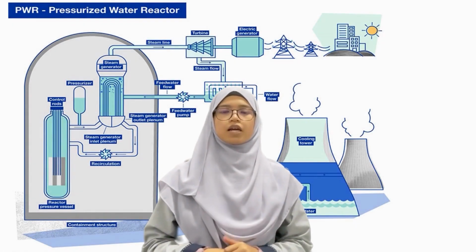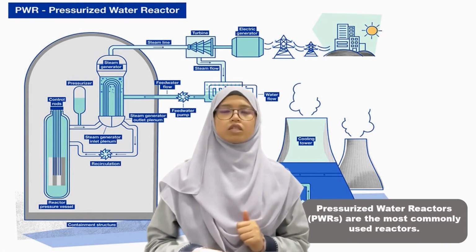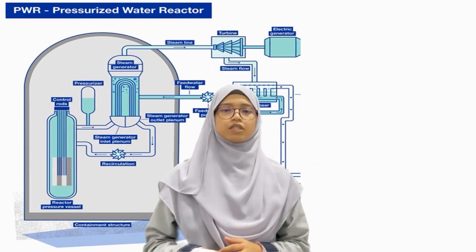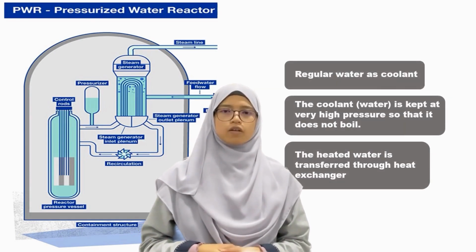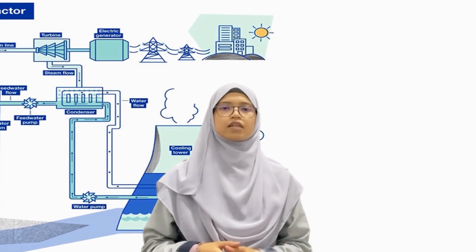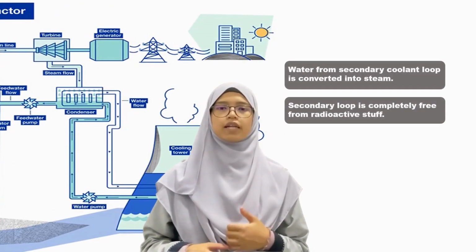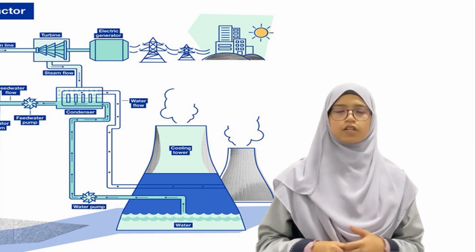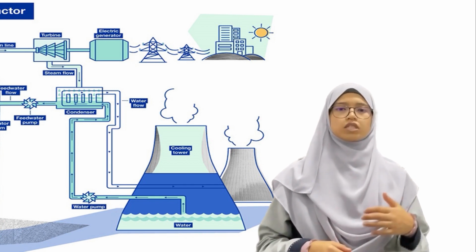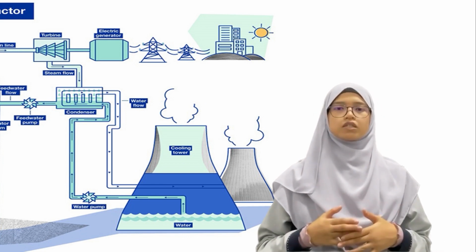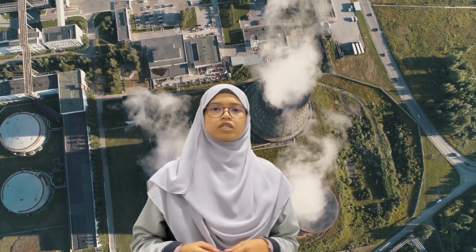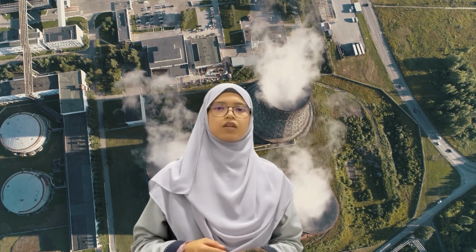Basically, a PWR has two water systems. One is called the reactor or primary system that retrieves heat generated in the reactor. The other one is called the turbine or secondary system that produces electric power with steam generated by that heat. This heat is transferred through the steam generator to the secondary system water to generate steam, and eventually to rotate the turbine to generate electric power. As the primary and secondary systems are separated, the secondary system through the turbine is not contaminated with radioactive materials.